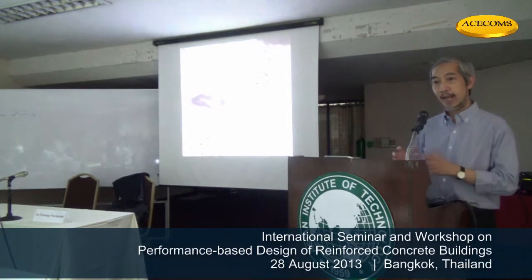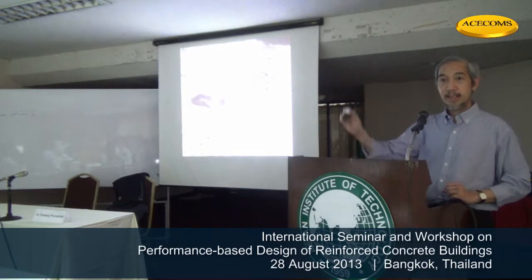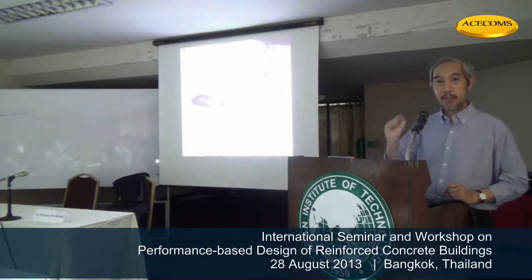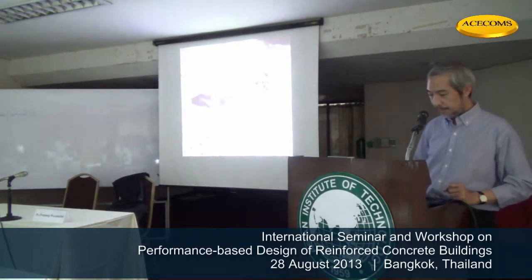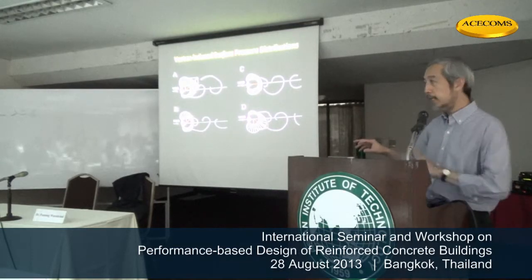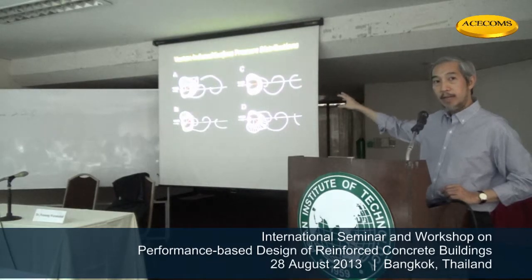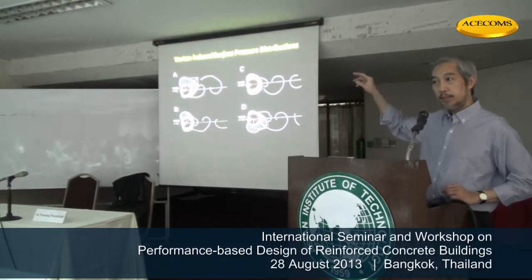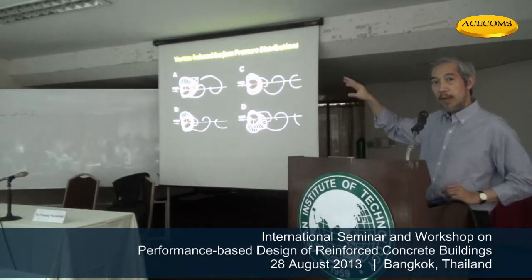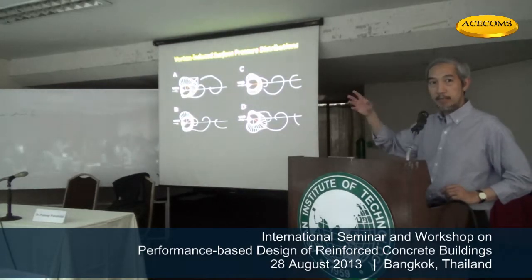So whether it's large size, like island size, or small size, like this, you can create vortex shedding in the wind stream. Now the vortex formation behind this will create a change in the pressure around the body. The pressure change will vary with time, but it will come back to its original form. It means a periodic change in the pressure pattern.